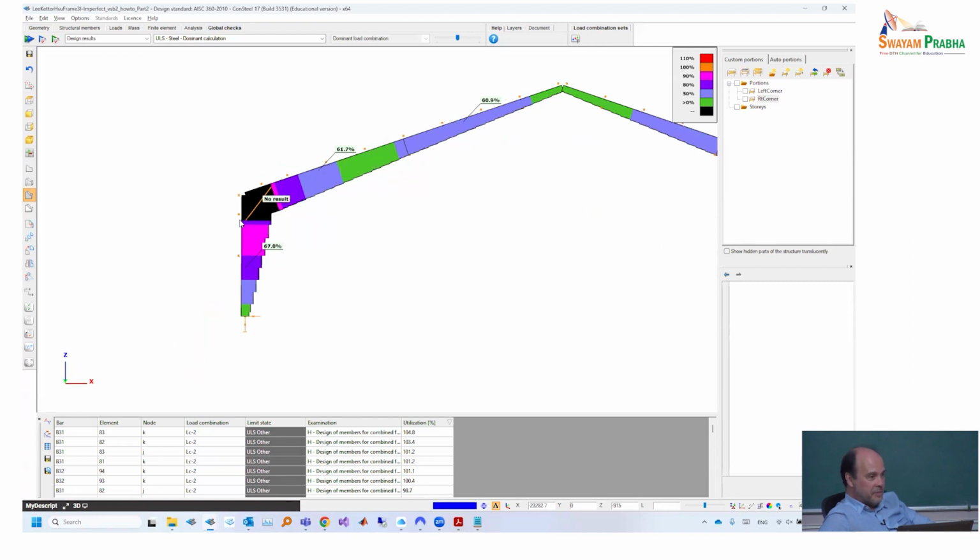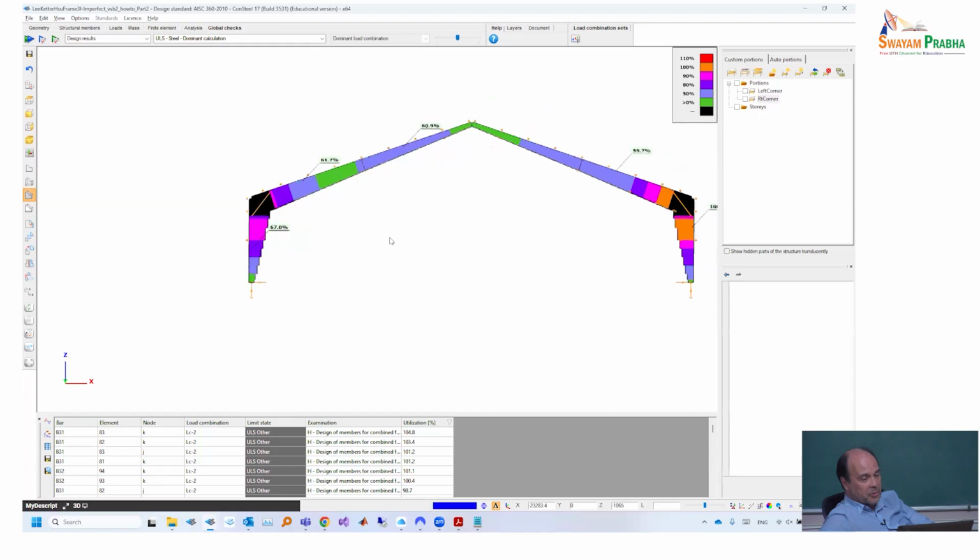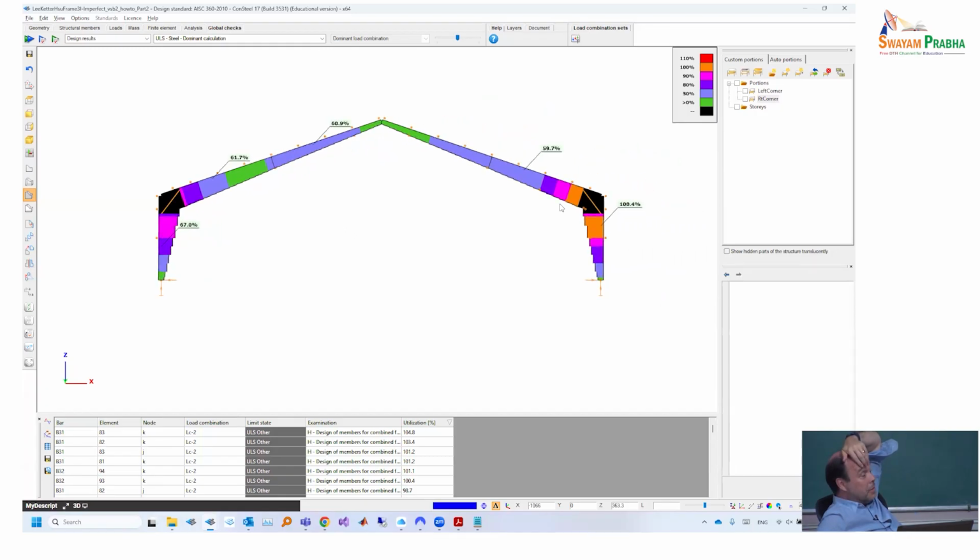So this is the moment where we are adding an additional constraint bar into the stiffness matrix of the system, which will be the leading information regarding verticals. We don't let the beam elements do the job because they cannot. And we inject additional information about the compatible deformations. Yeah, it's very interesting, and I'm pretty sure that no one is aware of that. So it's not only more extra welding cost, but it has also a beneficial effect. But just people still consider a hinge there.